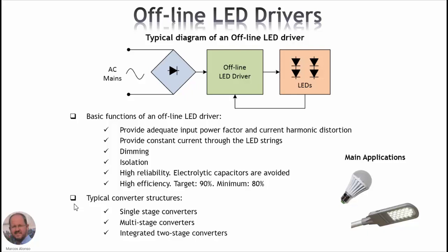The second solution is to use a multi-stage converter with 2 stages or 3 stages even, in order to improve the behavior from the input and also from the output, trying to use specialized converters for each function. And finally, we have the third possibility, which is the use of integrated two-stage converters, trying to reduce the cost and the complexity of the converter while keeping good characteristics of the driver at both the input and the output.